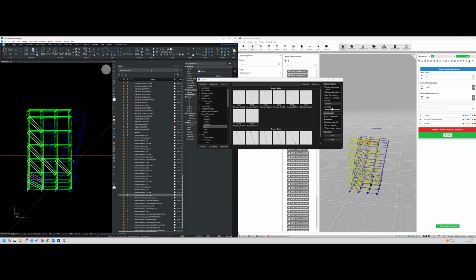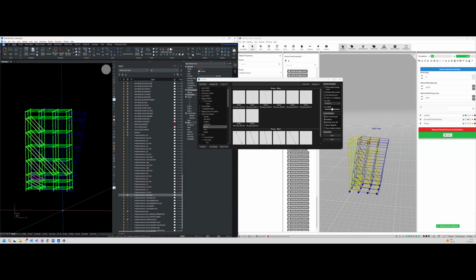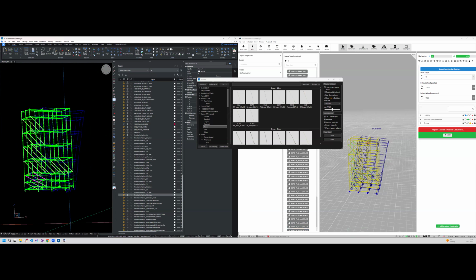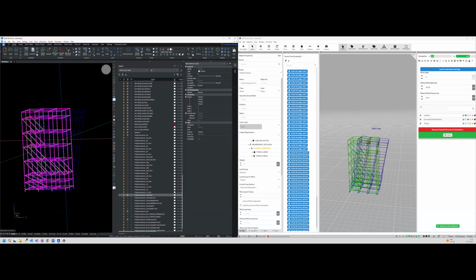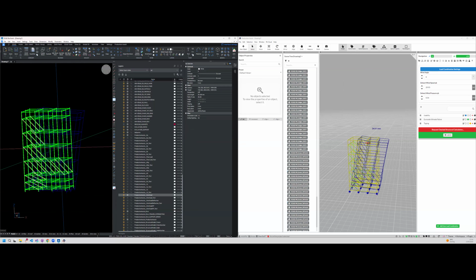And that's basically most of the things that you're now doing with Production Assist. Now we have a structure that is like 63% used just for the wind load, which is quite good. And now we want to have a little bit more of a look at the wind load. Currently, the wind that we have in here only applies to the tubes, which is fine because right now we don't want to cover this. That's also possible, but one step after another.